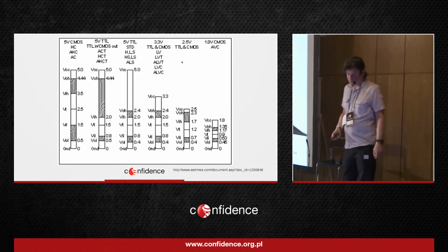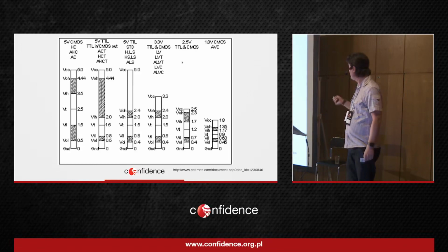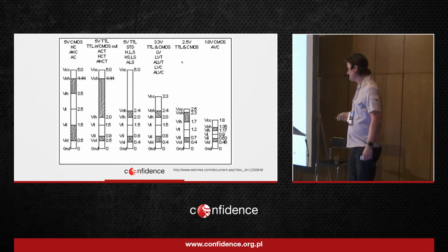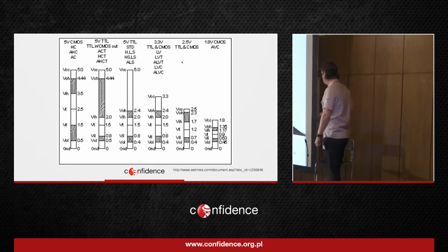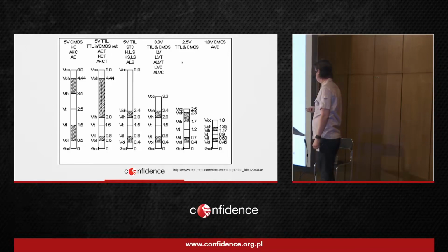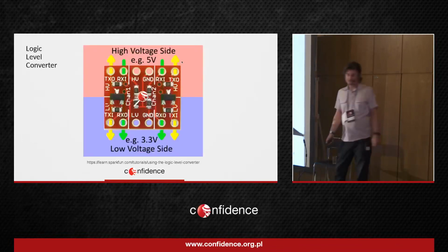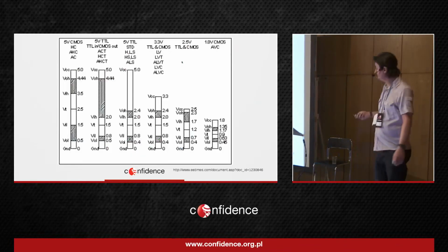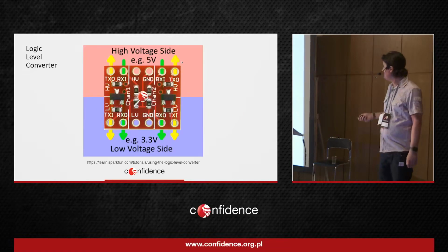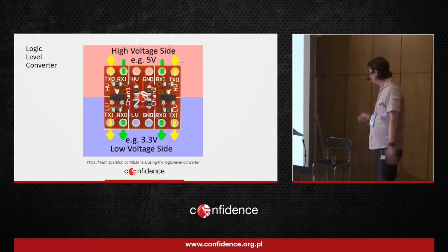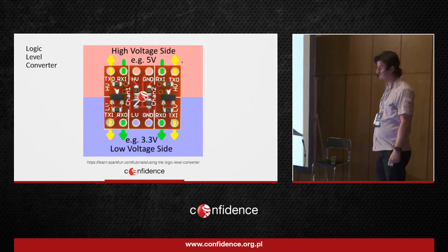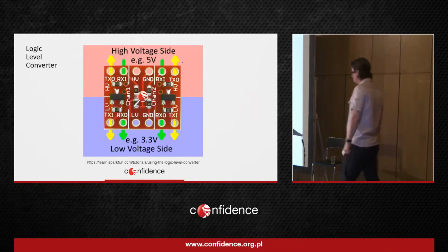Okay, the other one, 1.8 volt, this is getting popular now. And as you can see, it's incompatible with any of these standards. So if you want to connect this kind of device, which may be some Odroid or maybe something else, you will need a logic level converter.